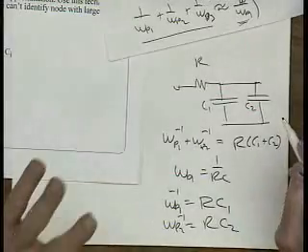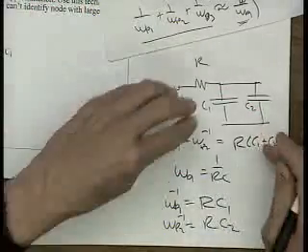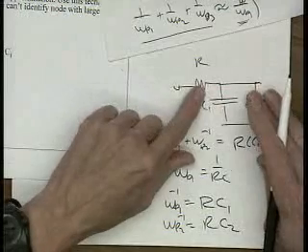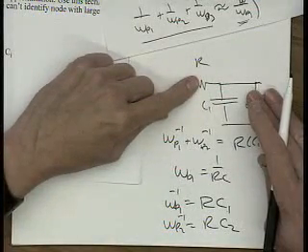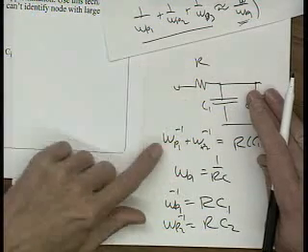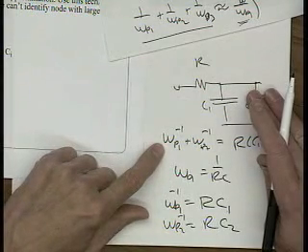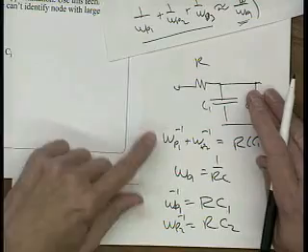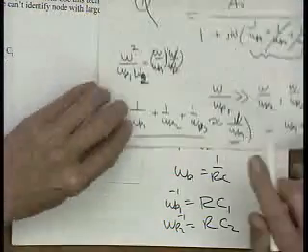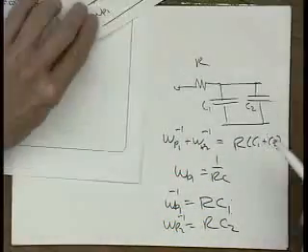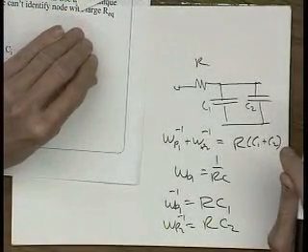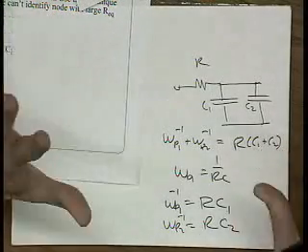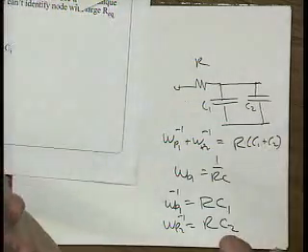So, a couple things going on here. By taking each capacitor individually, finding the resistance driving it, and summing up all these time constants together, under the assumption that one pole is dominant, we can get an approximation to the lowest frequency pole. So you get that? That's basically the zero value time constant analysis approach.